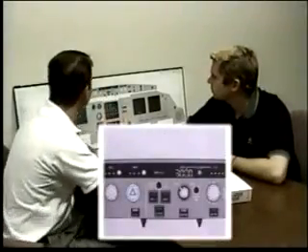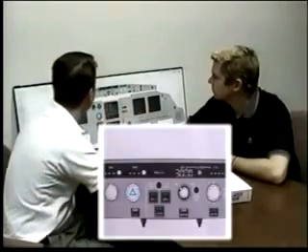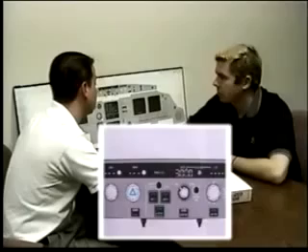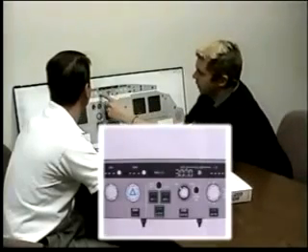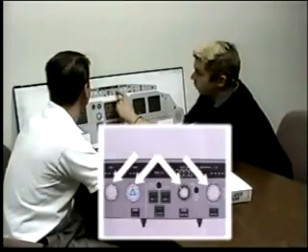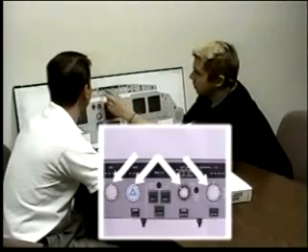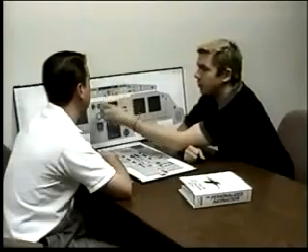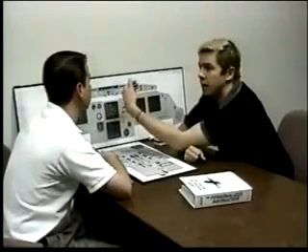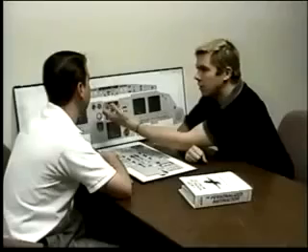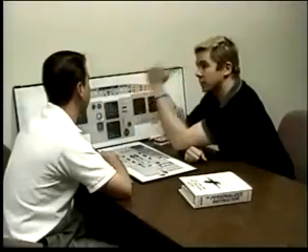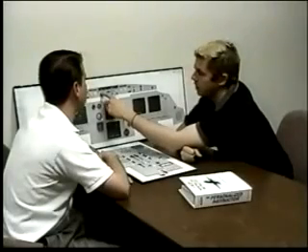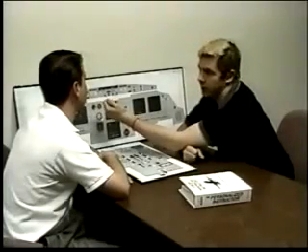Your FCU panel, starting left to right, walk me through the FCU panel in which you get managed speed versus selected, heading versus LNAV, and so forth. Sure. So basically we've got these buttons here. There are these 4 buttons, or knobs, truly. Whenever I push, I'm basically telling the airplane to calculate what I want, and I'm asking for a managed mode. When I pull, I'm saying, I've got it, I want it, select it. So whenever I push, I'm asking for a managed speed. If I pull here, I'm asking for a selected speed.